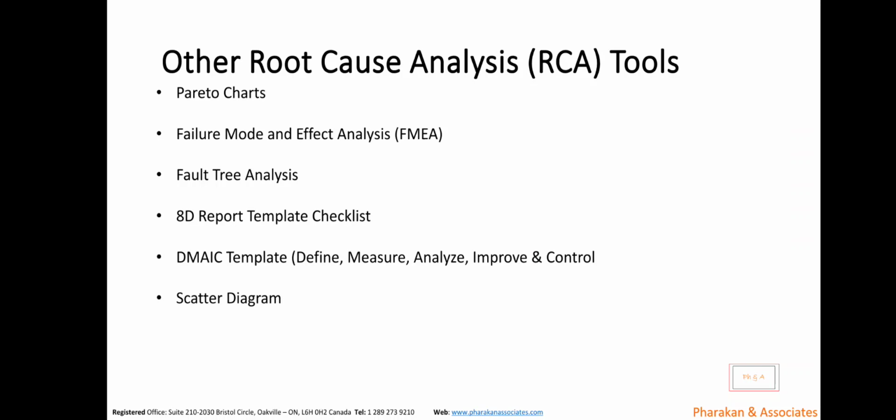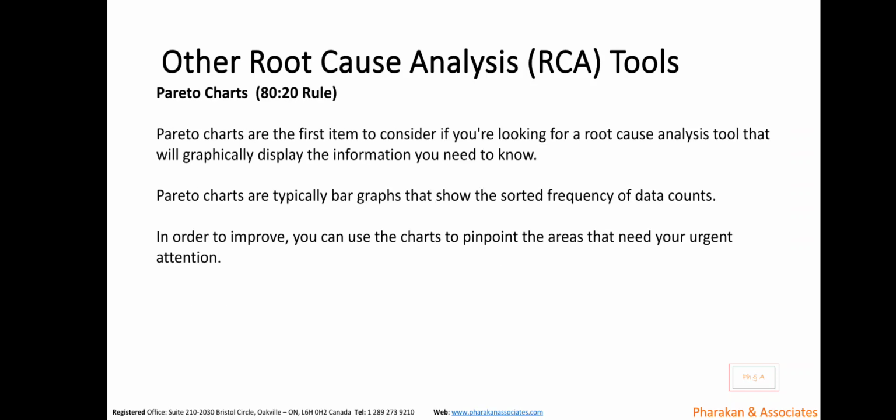Very great tool indeed. In addition to this, there are a few other root cause analysis tools. So we have the Pareto charts, like I mentioned, basically focusing on where the majority of issue is coming from. And the Pareto chart largely works based on data. You have the failure mode and effect analysis, the fault tree, 8D report. Let's take a look at one or two of these ones and then we pause for today. So the Pareto, like I was saying, is just a tool that takes a look at data to pinpoint the areas that require urgent attention.